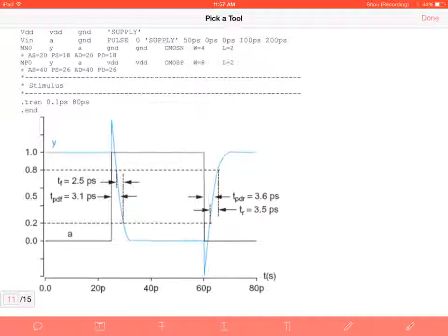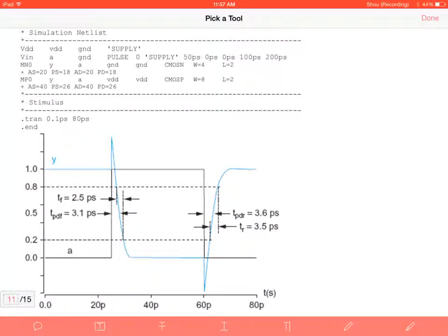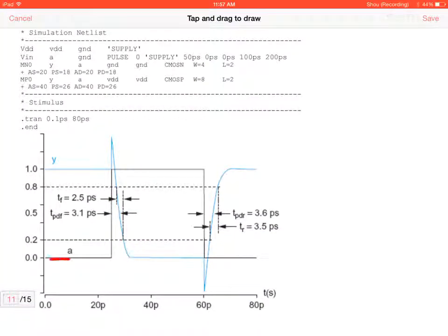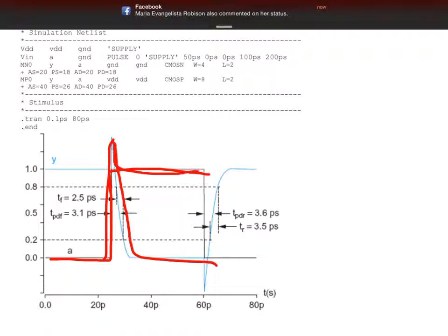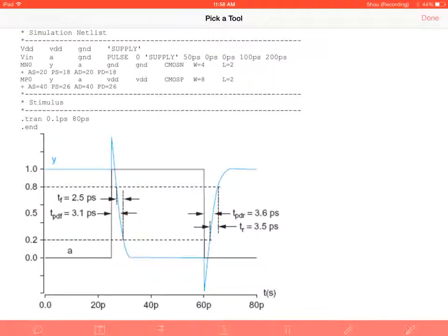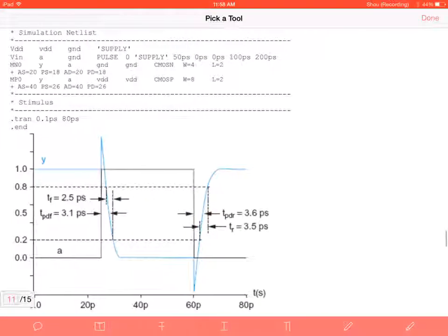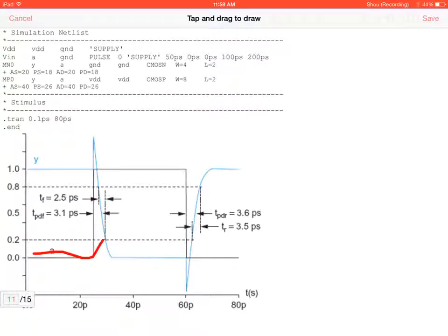So here, this is what's actually happening. We haven't properly accounted for it, so we just went straight from 0 to 1. My transistor went, holy crap. And then went back, peaked here, and then again, it doesn't quite work because it's getting overloaded, right? So that's why you want to have some sort of rise time, and that's why we actually calculated those rise and fall times in section 6. I'm sorry, in section 5.